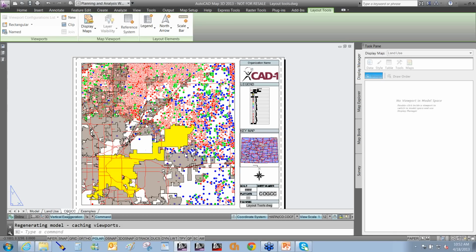Now, the scale factors aren't going to matter that much, so you can design the way that you want to. You can bring in the GIS data as state plane. You just don't want to snap to any of the data. It's going to be off just a little bit around here, just enough to mess you up. But then a lot of the GIS data isn't going to be terribly exact anyhow. So it makes for really nice displays, automatically linked legends, bar scales, etc. So you don't have to make any changes. And on that note, I'm going to start finishing up here. So if anybody's got any questions, now would be the time to pop up with them.